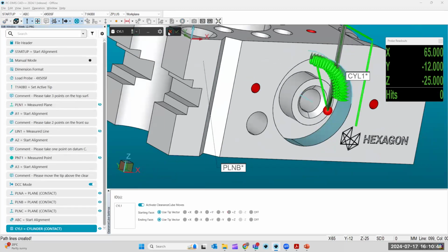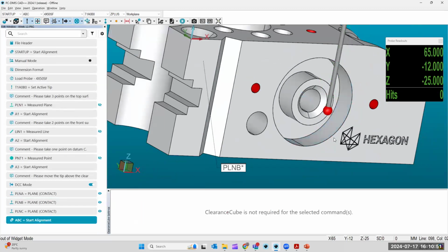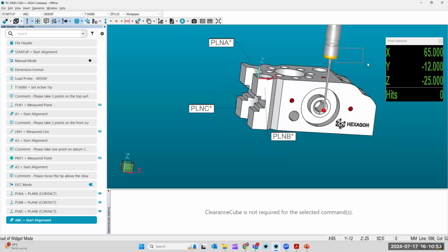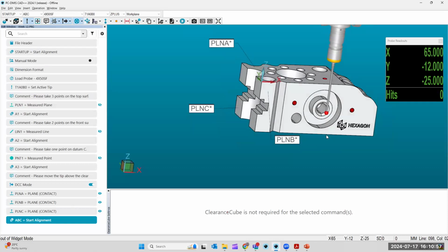So technically we should think about this before I did that. Okay, does that tool angle work for that feature? No, it does not. We need to be pointing towards that feature, which means we need to be at A90 and we need to flip all the way around at 180 degrees. So to do that, we showed you how to insert a tool change from the settings.